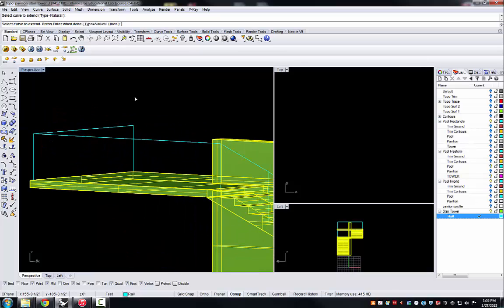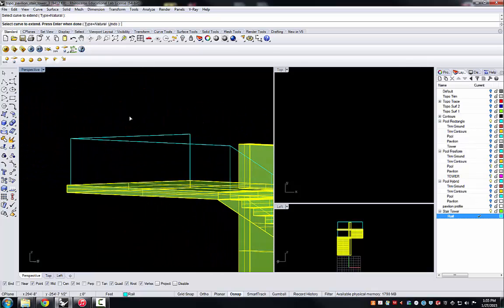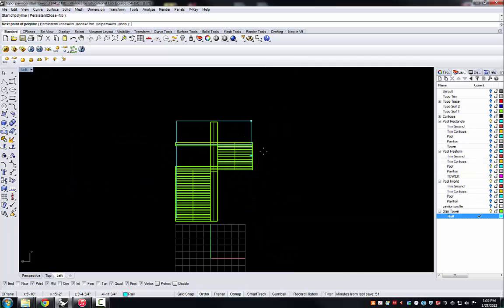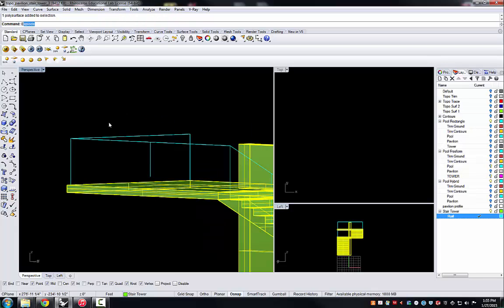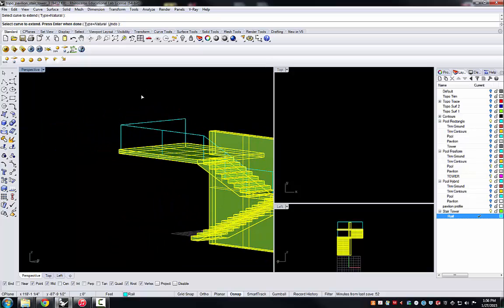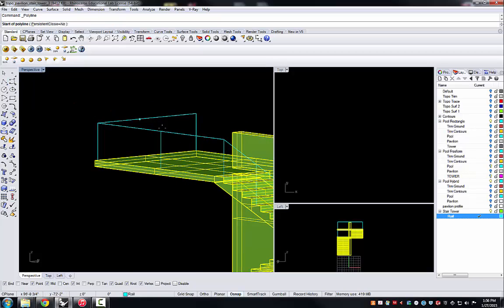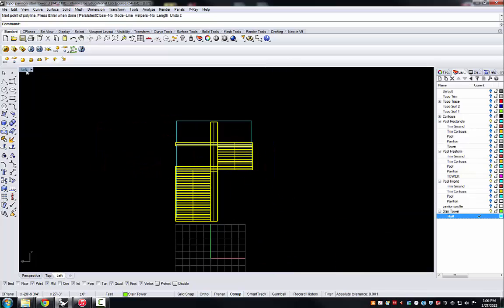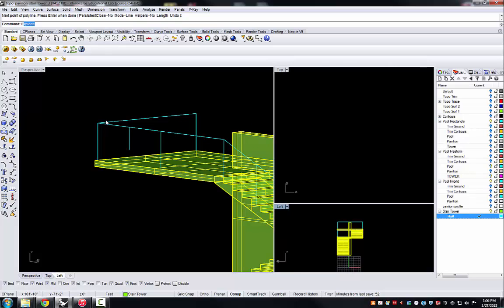And get a series of verticals, all of which will be used along with this top rail to create the handrail itself. So again, working from the midpoint, going straight down, coming back, doing an extend. And so there are a number of places that I'll do this. In fact, along this long edge, I'll want to create some more geometry. Another line. I can use this midpoint to, again, subdivide with a line that I will then extend